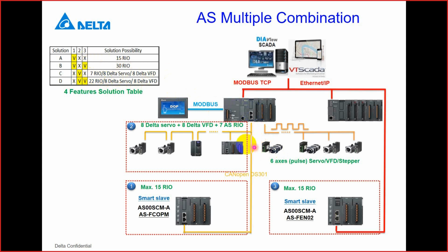Okay, another pure solution is the first solution, A. If we don't want to use the servo drive, we just use it for remote I/O purposes. Then for CANopen, we can extend a maximum of 16 remote I/O. Okay, so this is the first solution based on CANopen.